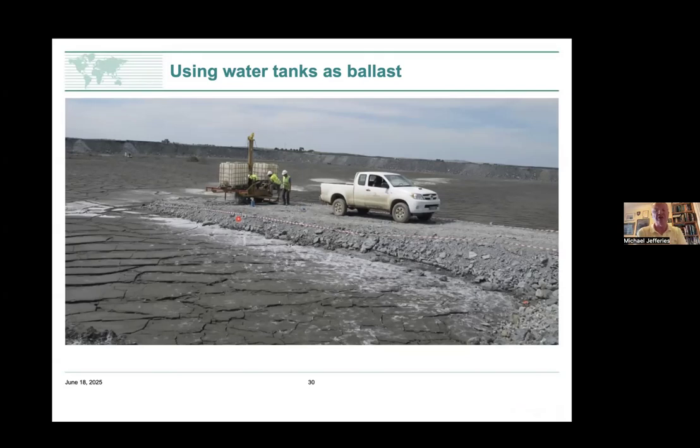The only thing we don't show on the screen, if you're out on a tailings thing, is that computers don't like bright sunlight and they don't like rain, so you need to perhaps have a small cabin or something like that, or sometimes we work in the back of the pickup truck with the air conditioning running. It's all very doable, and it's the nice thing about the CPT. It's continuous, or we take a reading commonly every 20 millimeters,